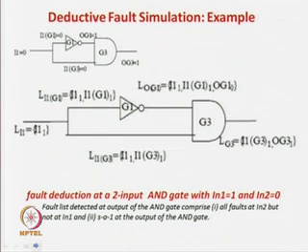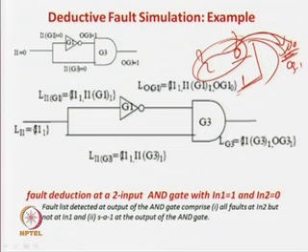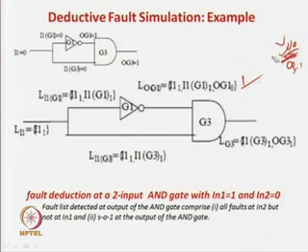Now there are two more rules which remain for an AND gate, that is 1 0 and 0 1. So we will see what the rules are for this. This is pretty obvious. Whenever this is a 0 and a 1, our intuition says what will follow. If this is 1, then whatever is here will propagate over here. So whatever is the fault list here can be propagated here, and the output is 0. So obviously a stuck-at-1 at this net is also detectable. The idea is that whatever is the fault list at this end can be propagated from here by the deductive fault simulation rule, and since this is 0 1, here you will get the value 0. So a stuck-at-1 fault at the output is also detectable. That is intuitively the case, and that is what is going to happen.